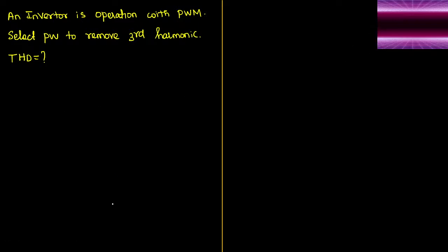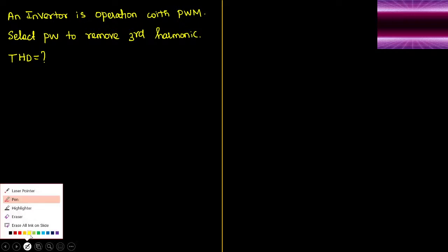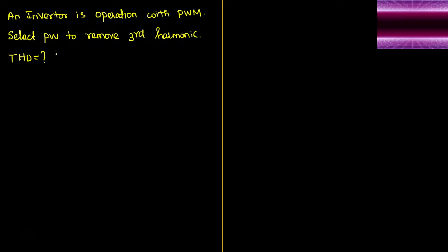See, this is single pulse width modulation. You know the answer for this question. I already told you, it will be 31 percentage. For three phase, it will be 48 percentage approximately. THD is fixed. Yes, very good, Geeta, 30.69. Anyway, this answer is fixed. It doesn't matter whether you are calculating or not. For single pulse, it is 31.